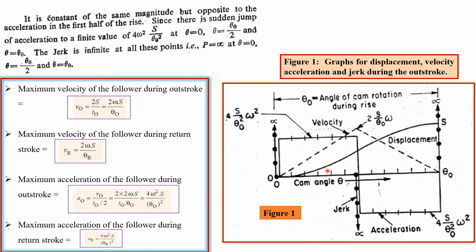When the cam has undergone a rotation by 20 degree, this much is the lift imparted to the follower. When the cam has undergone a rotation by say 50 degree, this much is the lift imparted to the follower. So if we just move through this path, ultimately this shows the displacement curve for the follower when it is supposed to be moving with uniform acceleration and retardation.